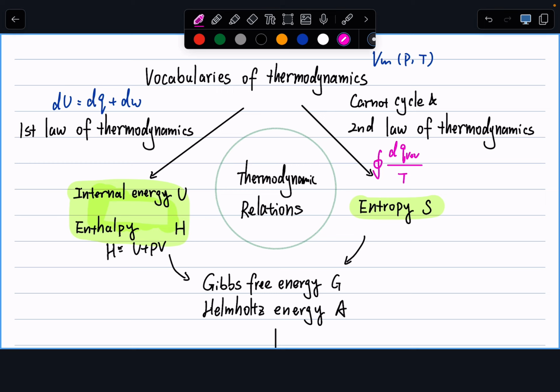All right. In our second law of thermodynamics, one of the statements of the second law says there's no heat engine that can 100% transfer your disordered form of energy, which is heat, into an ordered form of work output. Later on, using the second law of thermodynamics, we derived that eventually the delta S of my universe will always be larger than or equal to 0, where that equal sign is taken only when reversible processes are taking place.